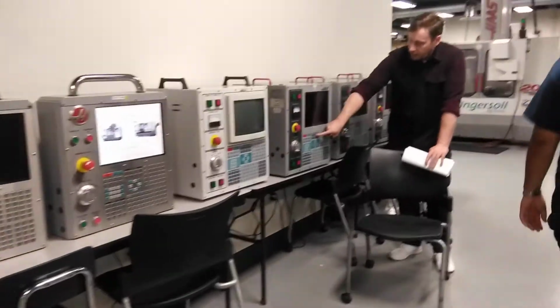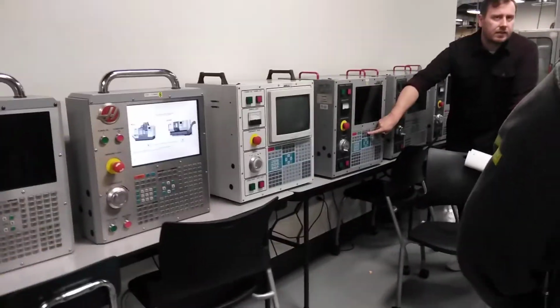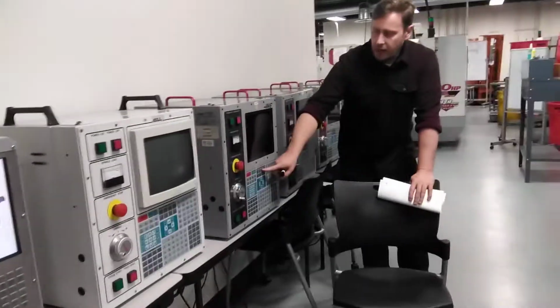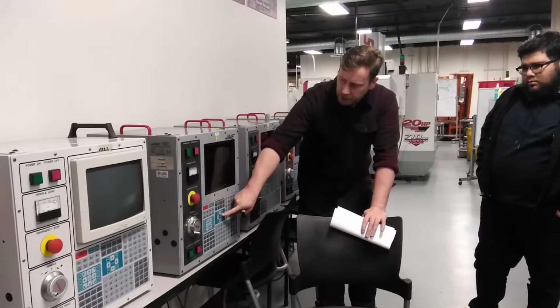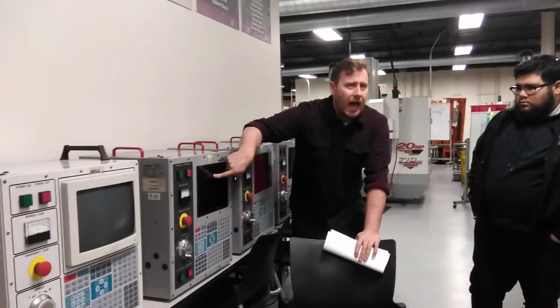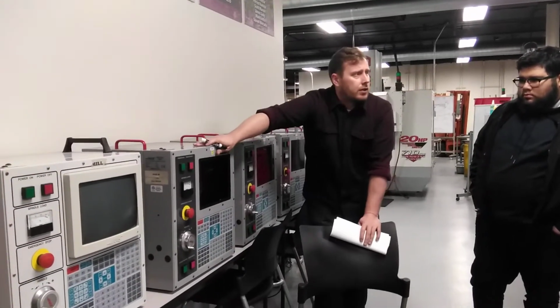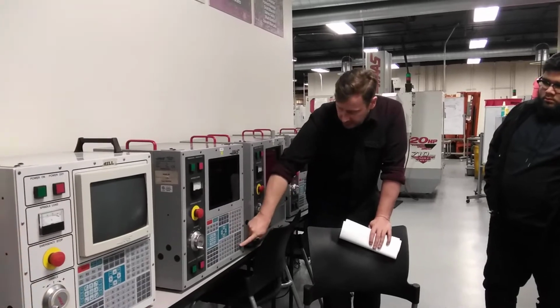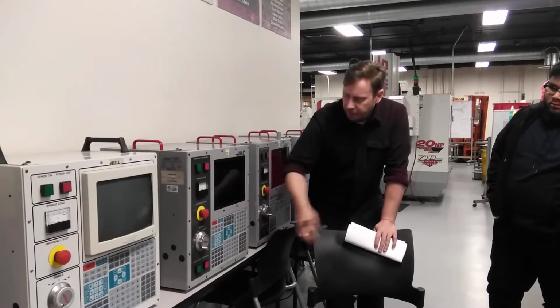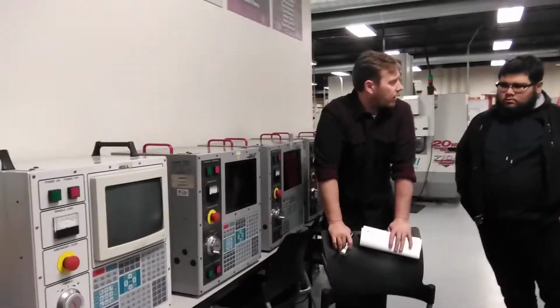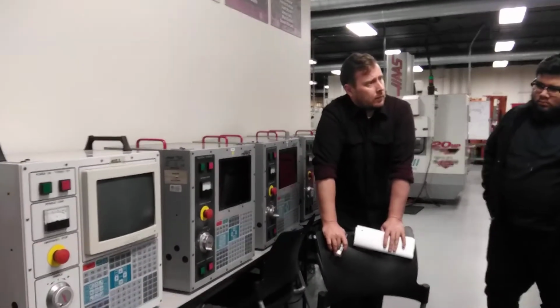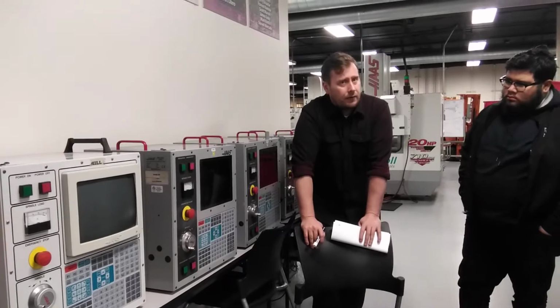So when we go to the offset page, you've got two offsets. You've got the work offset and you've got your tool length offset page, right? So we said earlier we're going to go to G54 and we're going to add some Z's. So here is where you'll put the negative 5 thousandths. That will drop all the tools down an extra 5 thousandths. Not just the fly cutter, every single tool.